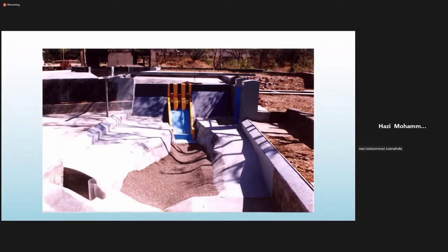This is nature, right? In nature you are building a dam, and this is the proposed design. So how will we change it? It is the same as the Doliganga: the jet is going and hitting this right bank. So what was the solution at that time? The only idea was that the dam axis is tilted a little bit. Okay, next slide please.